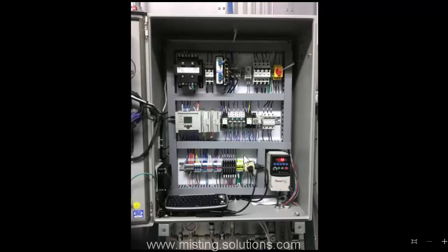We don't want the output fluctuating up and down with every little change that we have within the DC signal coming in. If you think about it, the room just does not change that fast either. It's a large room with a constant relative humidity in it, but it does have a lot of air volume, and it is bringing in a lot of fresh air. So there is change, but typically that change is quite gradual. So every 30 seconds, this controller looks at the signal and says, oh, I've got to increase my output capacity or decrease my output capacity. And it does that basically by opening the 4 solenoid valves or zone valves for the different zones of humidification.